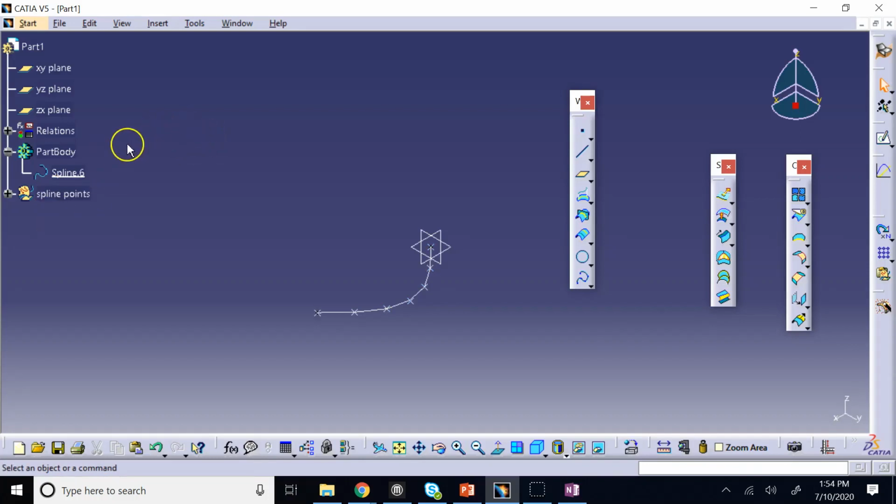So if one file is referring to these points under the tree, but now it says, okay, I'm using these points under the tree. Now I cannot find those points under the tree anymore. Somebody moved them. And so that entity, which is here, the spline, gets confused. I cannot find the points I need anymore. Where are they? And so it gives you the error. But here, I first copied those points into this folder, and then I define my spline. So spline knows that the point it needs is what?